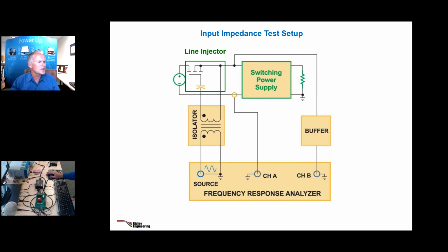Is a 1 megahertz line injector sufficient for most purposes? That's what we have. Ours doesn't go beyond 1 megahertz. You'd have to build a much more sophisticated amplifier to do higher frequencies than that. But you're trying to measure the control frequencies. Beyond that, you're not going to do it this way, you'd be using something else. But this is a way to get the PSRR if you need it without spending too much money on the high power sources. I want to turn that off now because this one is not heat sunk fully.